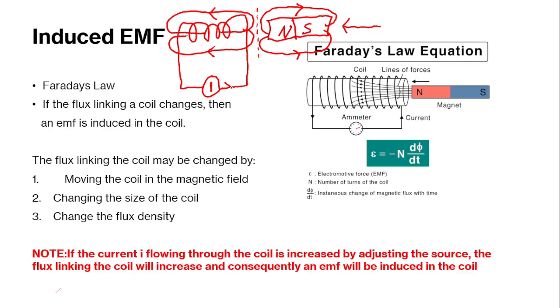So if it is going to the right, remember the current will be going this way, right? You see that going on? So the current will go up, and it will go this way, then this way, then this way, and then back down here. Right? So you're seeing when all these little magnetic fields aid and strengthen each other, the overall direction will be this way. It will strengthen a right to left direction. Okay. So this galvanometer will actually deflect this way. That makes sense? Yeah. So that is when it is moving towards.